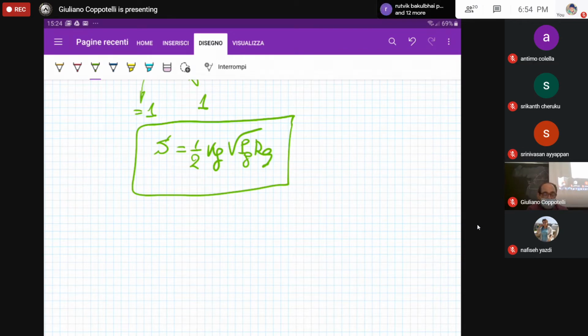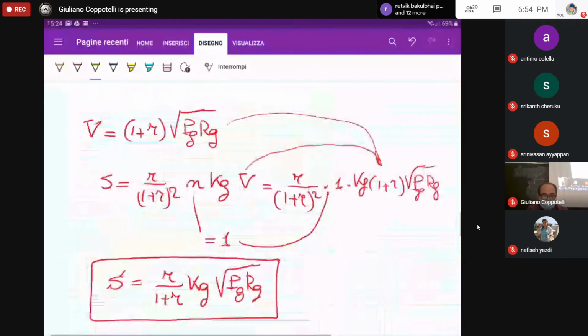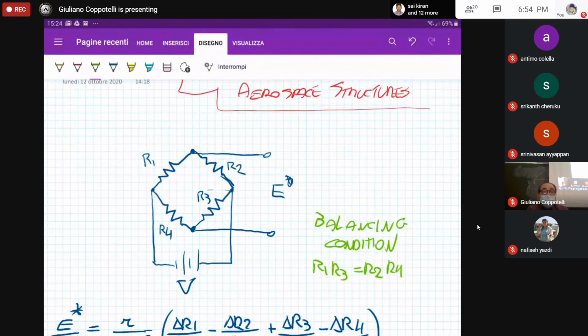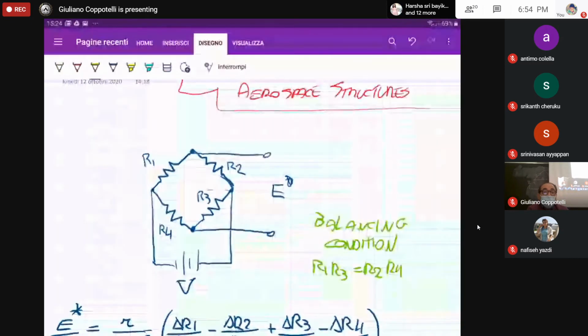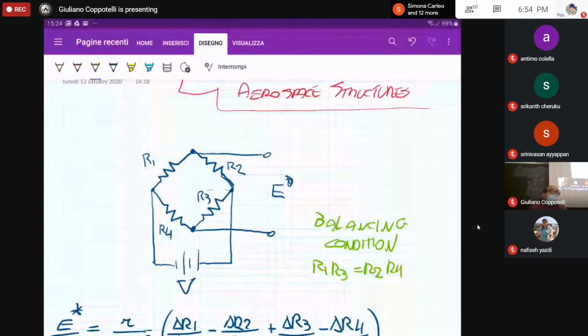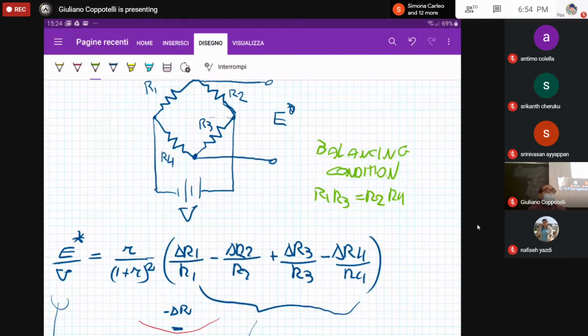Okay, so once again, if I go up to the circuit, instead of using this compensating strain gauge in leg number 2, that is, instead of having this strain gauge in resistance R2, we are putting that in resistance R4. These are the only two places, by the way, to put this compensating strain gauge, because if you go back to this equation, these are the only two options that we can have in order to take out something from the leg number 1.